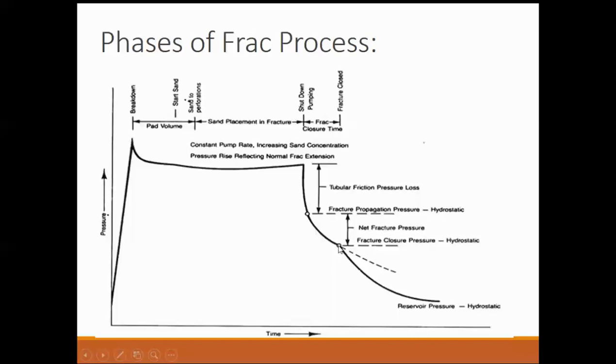If at any time during your job the pressure drops below this point, your fracture will close. So you should always be aiming to keep your pressures above this closure pressure. Once you know it, you can design your jobs better.